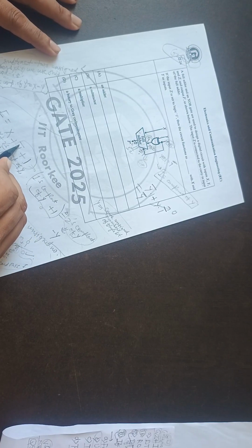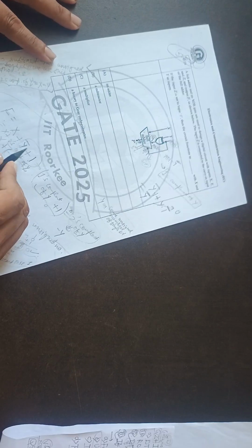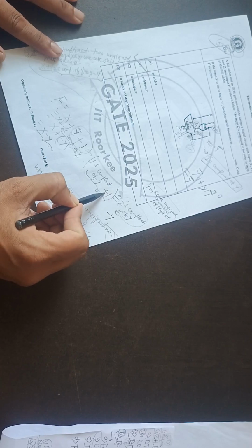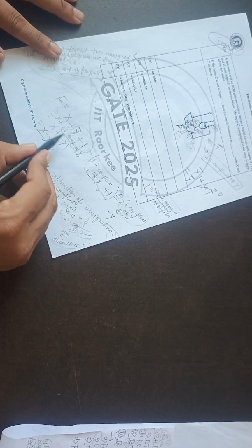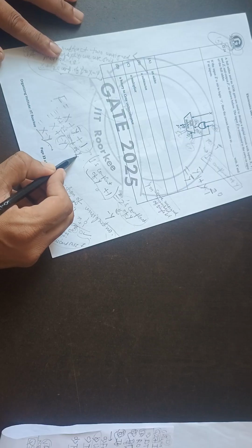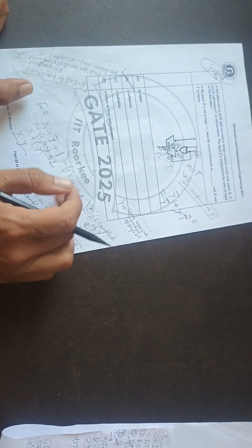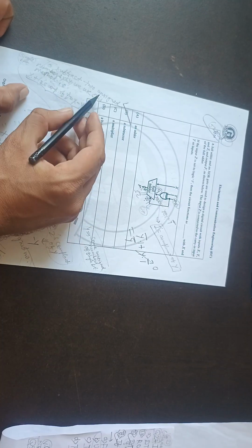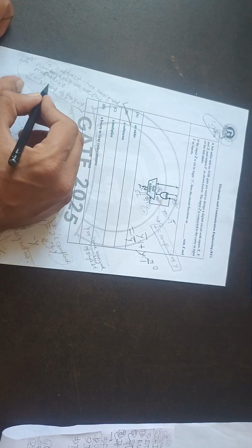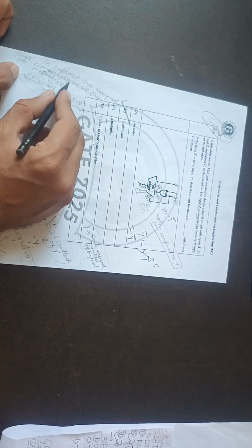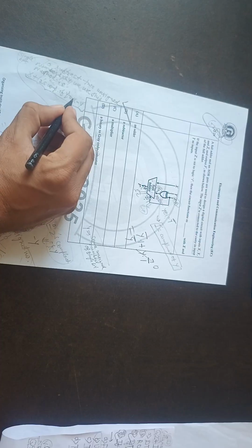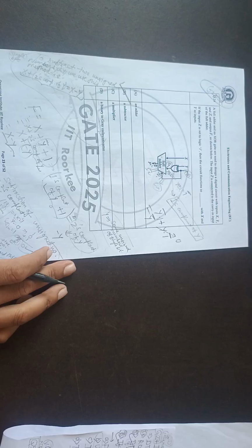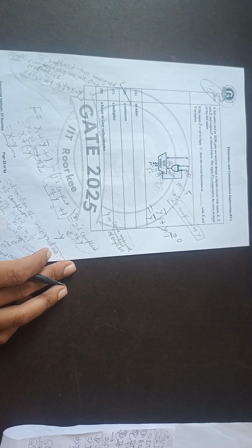Now Y bar can be treated as the 1's complement of Y, and 1's complement of Y plus 1 is the 2's complement of Y. So this is basically X plus 2's complement of Y. Now in number systems we learned that to subtract two unsigned numbers X and Y, we use X plus 2's complement of Y. We take the 2's complement of Y and then add them, so this will give us X minus Y. That's the way to subtract two unsigned numbers using 2's complement.